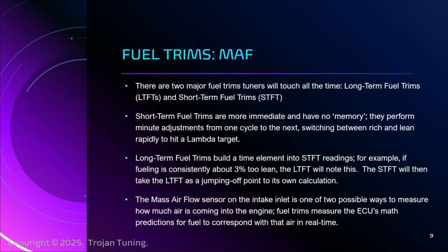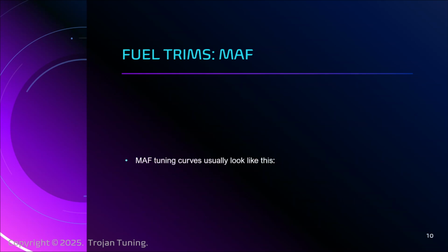The problem is, what if the model isn't correct? What if it's a little off? That's the whole point of the fuel trims, because if we know the air from the math and we know the fuel, we can then measure and understand if we were off a little bit, and then we can constantly make adjustments that move us towards optimal power production. It's the whole point. Okay.